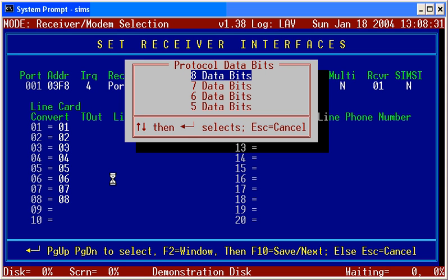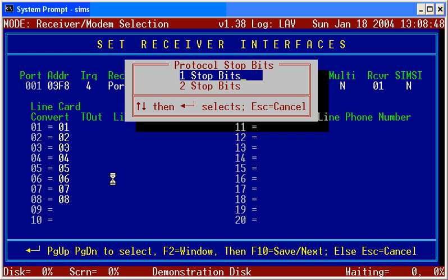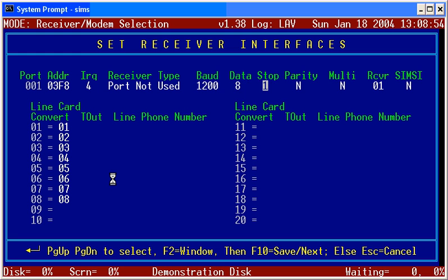But there are some that are 11-bit transmissions, so you really have to pay very close attention to what it is. 11-bit, of course, doesn't work through modems. There are lots of reasons why it should be 10 bits, but we're going to have to understand that there are things that we have to deal with there. The number of stop bits, we've mentioned that. There's usually one or two. I've never known of any exceptions to that. In fact, the protocol doesn't allow for any.